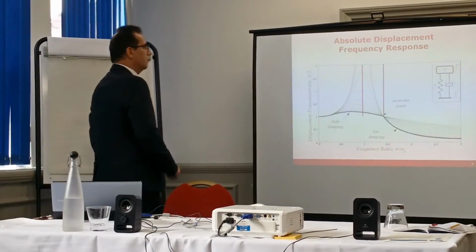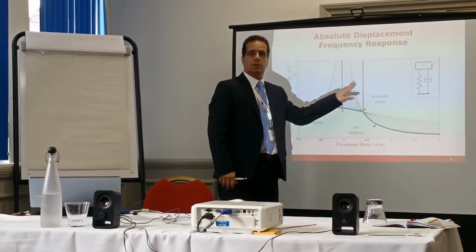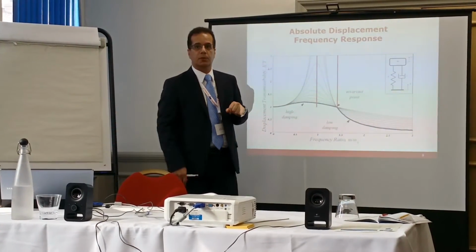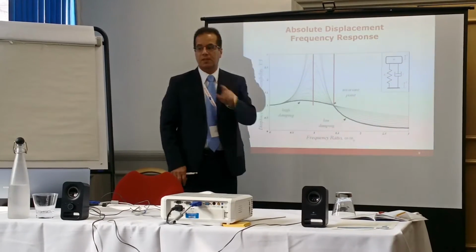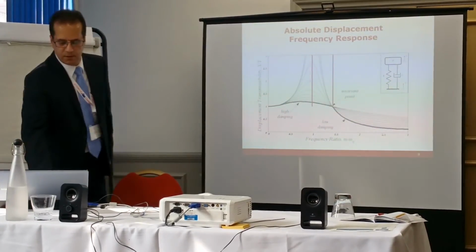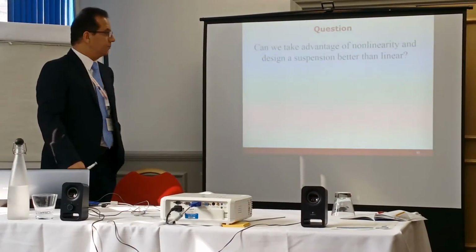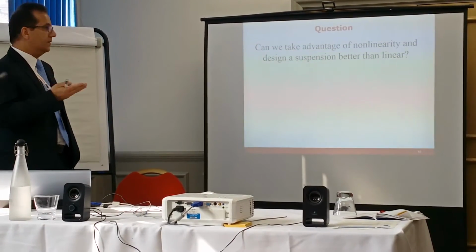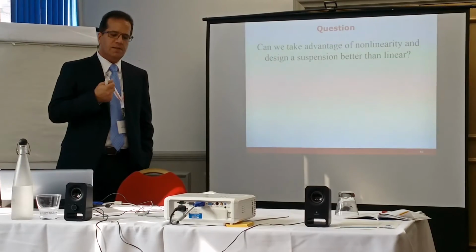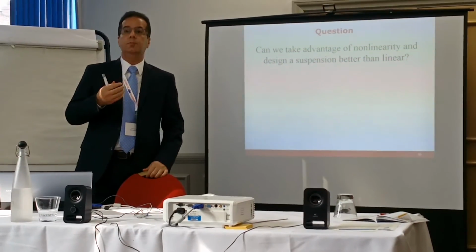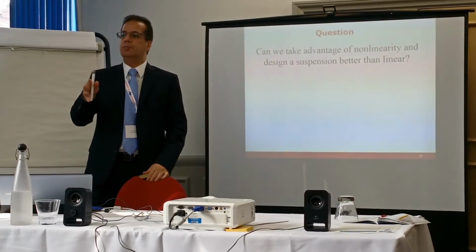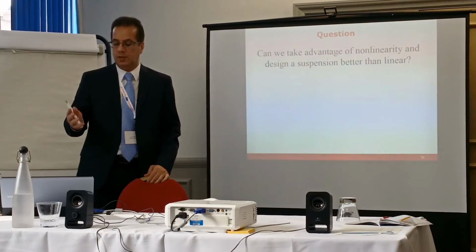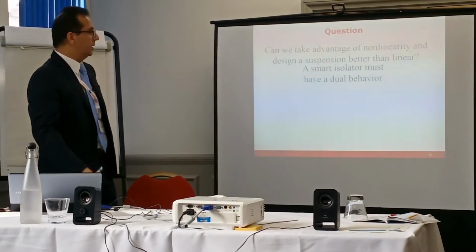So we are switching from a frequency-damping relationship to an amplitude-damping relationship. The reason is that frequency is not easily detectable unless we have a continuous vibration, but amplitude is detectable instantly. So that's what we are going to do. Question: can we take advantage of nonlinearity to design such a system? The system is going to be smart, but passive, meaning it's going to switch between high and low damping by itself. We are not going to use any computer. That's the whole purpose, to make it cheaper.